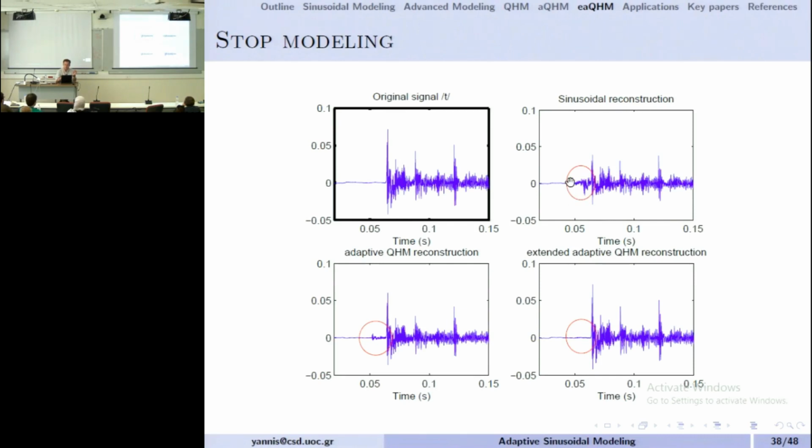So where is the problem? The problem is that you don't have a big burst here, a big change in the frequency. So you don't have clean t, k, p sounds. And these are very important for the intelligibility and the quality of the synthetic speech. So when we do the adaptive quasi-harmonic model, we improve this by far. That means we remove energy from here to here, so that now we have a very good click, the release of T. And if we do the extended one, mainly there is nothing here. All the energy is here now. So that's good. A clean, intelligible sound.